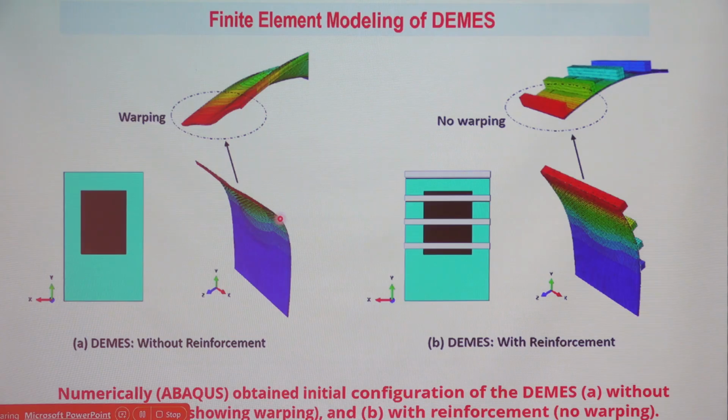So at the point after which increasing the number of elements gives you the same displacement, select that number of elements for the entire simulation. This analysis is called mesh convergence analysis. You are getting my point?